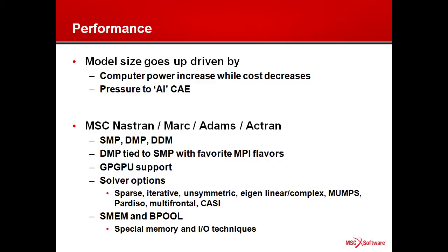A CPU, standard is what, 2-4 cores? You want to use those with memory, shared memory parallel, distributed memory. You break the model up into pieces. It's one of the favorites for nonlinear analysis. They call it DDM. You got to tie them together so they can work together.